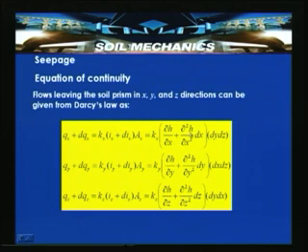That can be written as kx into ix plus dix, where dix is the change in hydraulic gradient, written as ∂²h/∂x² over a length dx. This simplifies to kx into (∂h/∂x plus ∂²h/∂x² dx), over the area dy dz. Similarly, we can write qy plus dqy and qz plus dqz.